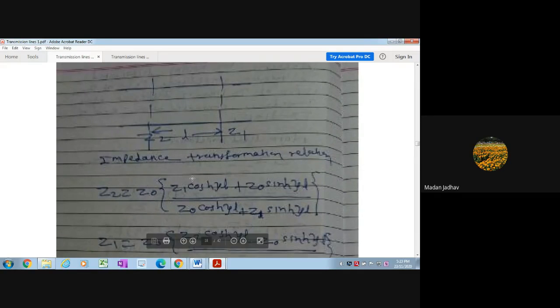We say that the transmission line is a 50 ohm, 300 ohm, or 75 ohm transmission line, which means that is the value of the characteristic impedance of that transmission line. This is one of the important parameters in the specification of a cable or transmission line.